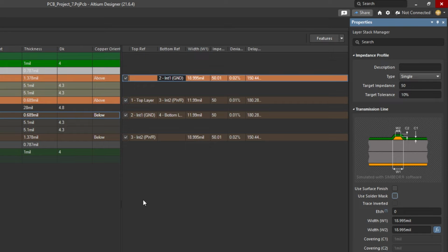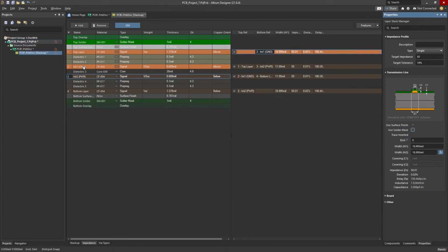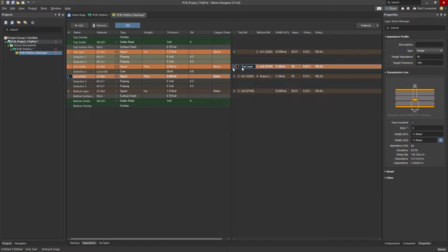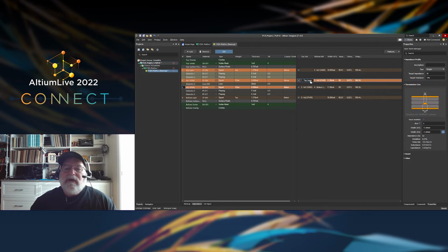And before we move on from here, I'll show you if we have an inner layer like this one here. This is layer 2. We have the opportunity of a plane above and a plane below. And so here I'm defining the top reference layer is on layer 1 and the bottom is on layer 3. And Altium is taking the Stackup information and automatically porting it over to the 2D field solver. And here you see the picture. Hey, look, I've got 2 prepreg layers over here. I define the dielectric constant here, and I have 1 core over here. And there it is. So I've matched that geometry.